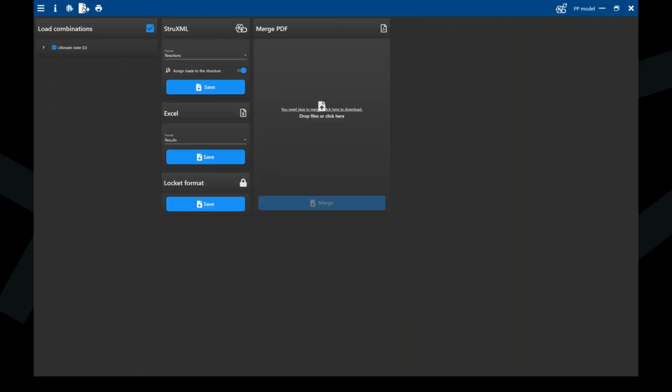Then we can export. So now we can generate those extra finite element models based on new load takedown. So there's an export button, and here's the things we can export. The reaction means that if we have a foundation model, we can export the reactions to the foundation model with new plastic distributions. So we have moved those compression locations based on concrete capacity and the optimal overturning of walls. Wall elements, this is really handy if you want to do wall element design with the FEM-Design.